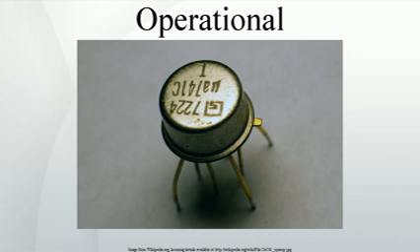Differential amplifier. A cascaded differential amplifier followed by a current mirror active load. The input stage, outlined in blue, is a transconductance amplifier, turning a differential voltage signal at the bases of Q1, Q2 into a current signal into the base of Q15. It entails 2 cascaded transistor pairs, satisfying conflicting requirements. The first stage consists of the matched NPN emitter follower pair Q1, Q2 that provide high input impedance. The second is the matched PNP common base pair Q3, Q4 that eliminates the undesirable Miller effect.